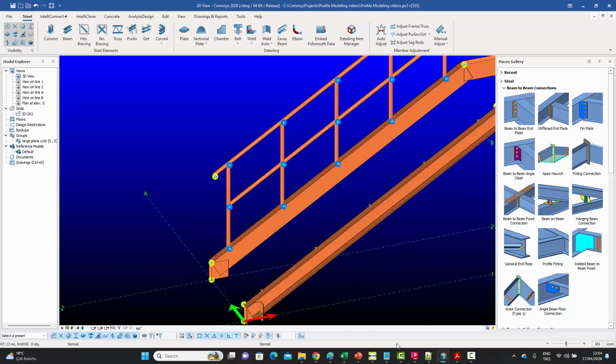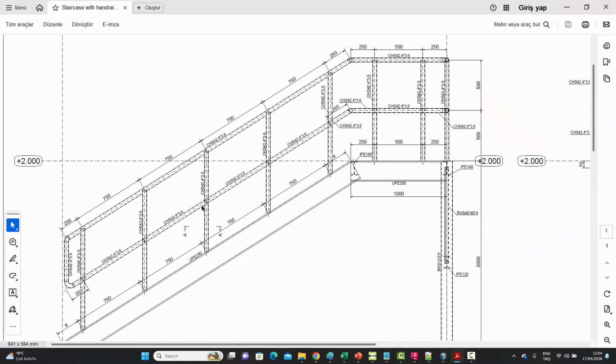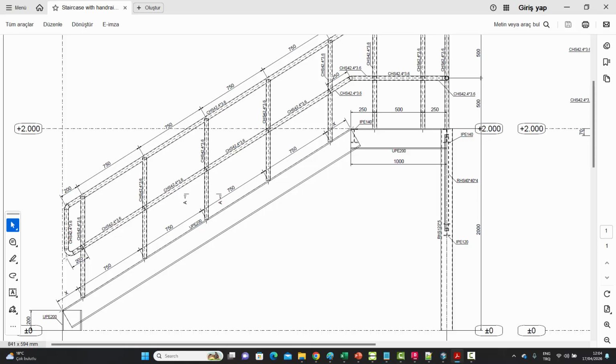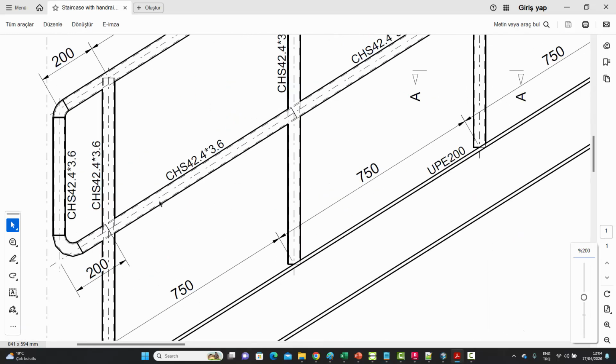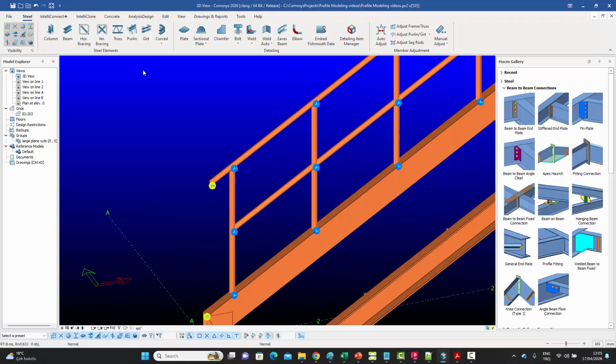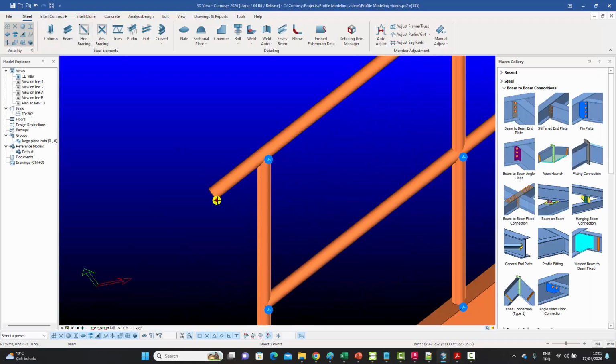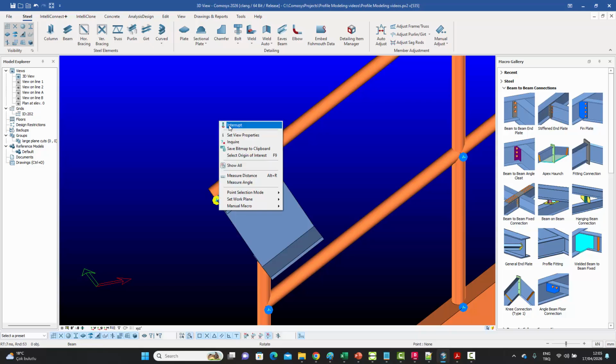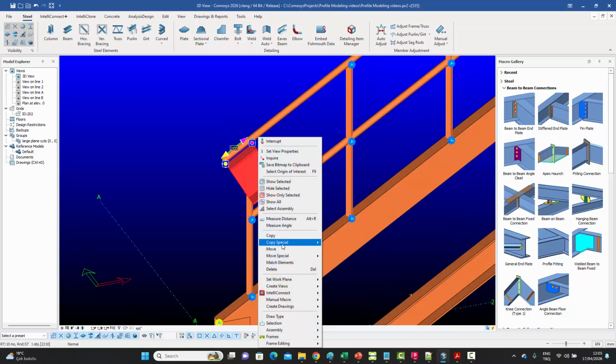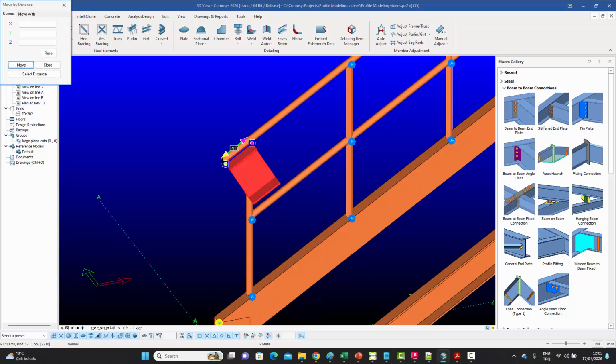What about, let's go back to the drawing. This one is a separate piece, by the way. It's not extended because this one ends over here. So there's a separate piece with a total length of 200, which needs to be entered at this point. An easy way to do that could be just enter a beam from here to here, because you know it's the same distance, and then just copy it, move it from there to there, like that, and you have it.